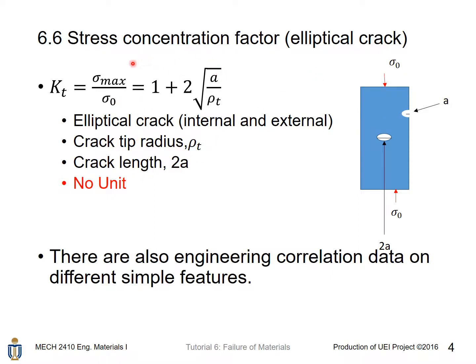This equation can be applied to both the external crack here and the internal one here. And Kt has no unit. This is just for an elliptical crack, and there is also other engineering correlation data on different simple features other than an elliptical crack.